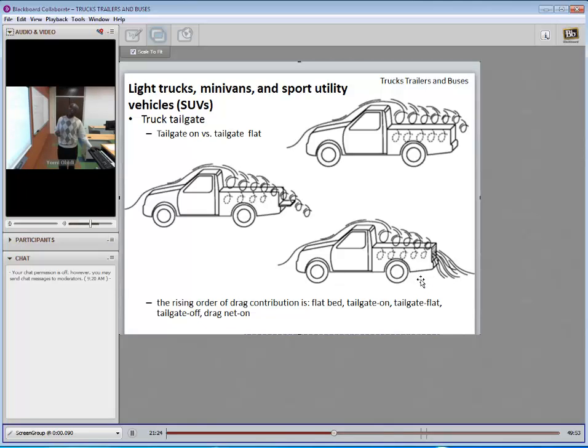So a drag net is lighter, that's true, and it might result in a reduced weight, but as far as aerodynamics is concerned, it actually increases the aerodynamic drag. So a way to compare the benefit of the drag net is to have a drag net of about the same weight, and you would not then see the benefit of weight that the drag net would have incurred. So overall, again, strictly from an aerodynamic point of view, the drag net causes an increased drag.